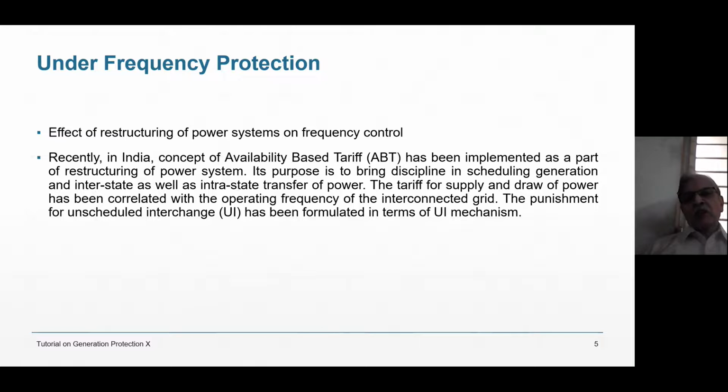If our power factor is 0.94 or 0.93, then we have to pay a penalty when the bill comes. But if we improve the power factor to 0.96 or 0.97, then we will get some rebate in the bill.